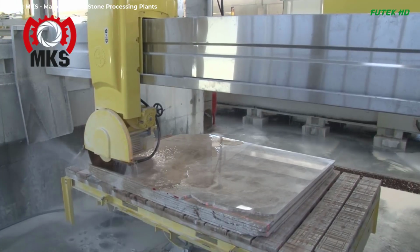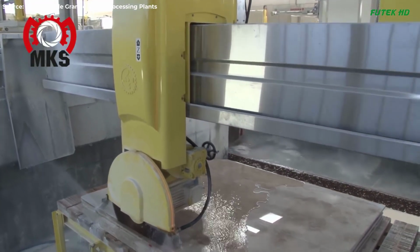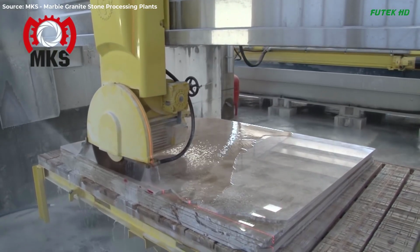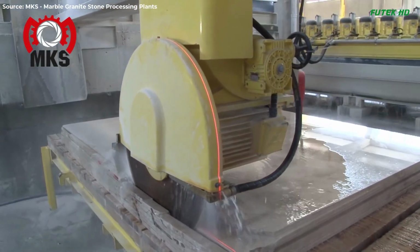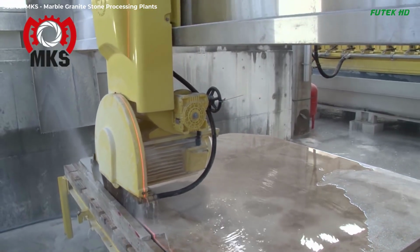This system ensures that the blade rack remains in a steady, linear form, countering forces from various directions during the cutting process. The hydrostatic linear bearings reduce friction, allowing the machine to operate at high speeds without vibrations, which is crucial for achieving smooth, clean cutting surfaces on the marble slabs.